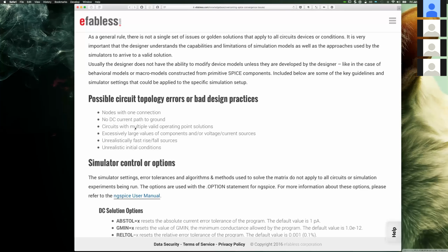It could be valid mathematically and valid physically. The danger is that you will assume that the circuit works in simulation, and in the lab you end up with something completely dead because it didn't operate. One of the valid operating points would be the zero mode, or a case where it functions at a different voltage or operating point that actually sticks there.